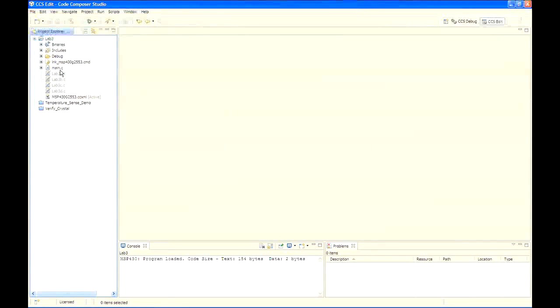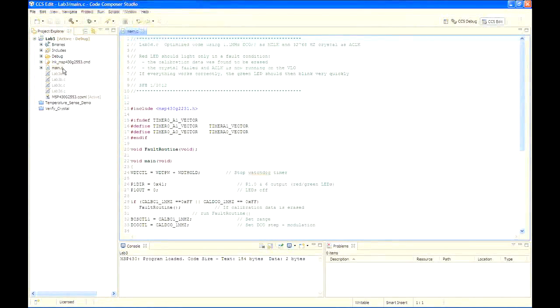Here, the lowest frequency at which we can run the DCO is 1 megahertz. So let's get started switching the M clock over to the DCO. In most systems, you want the A clock to run either on the VLO or on the 32 kilohertz crystal. Our A clock in our current code is running on the VLO, and we're going to leave it that way and just turn on and calibrate the DCO. That puts us at step 31 in the lab.